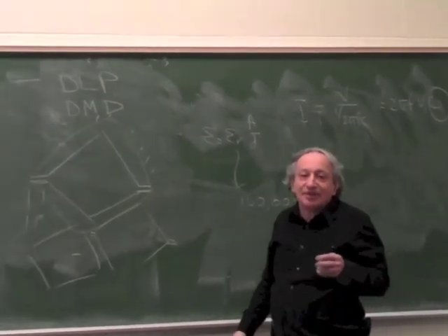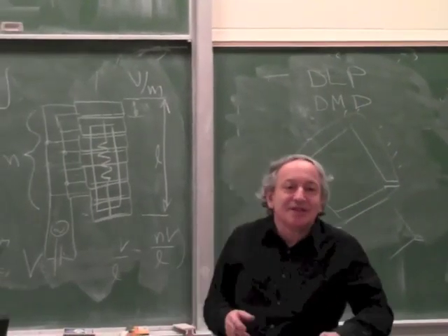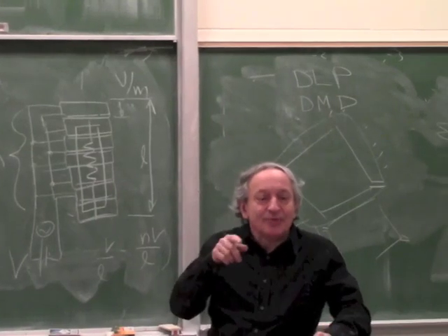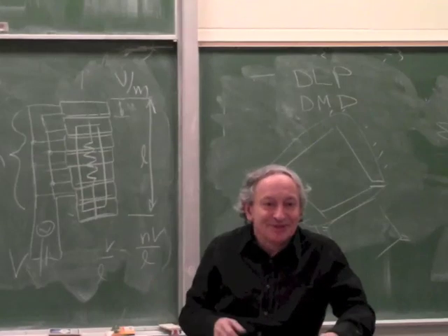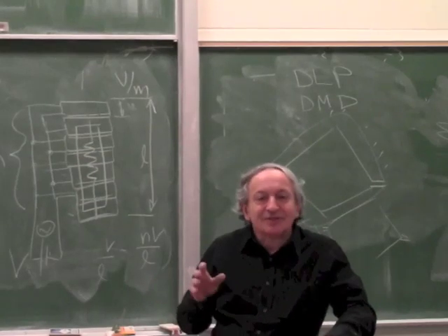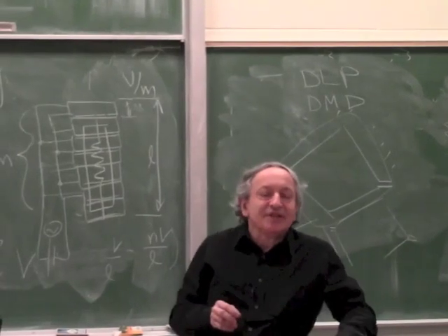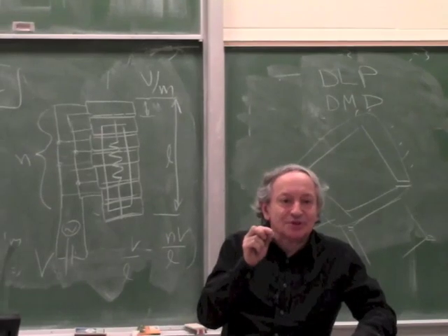But on the other hand, the magnetic actuator you also cannot drive very fast, because the inductance ends up a big number, like 2 pi F L. If you drive it at a very high F, you also have a problem. Okay? So both actuators have some limitations at high frequencies, but piezo is very nice and elegant because you can make very controlled small motions.